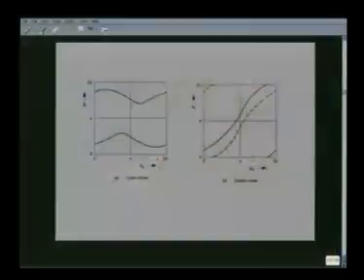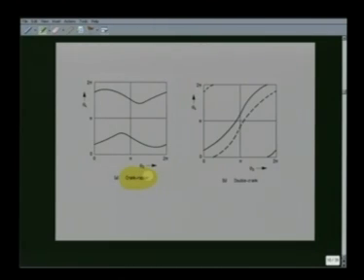For example, here we see what we call a crank rocker linkage. That means it is obviously a Grashofian linkage and a crank rocker, and theta 2 goes from 0 to 2 pi. And theta 4, because theta 4 is the rocker angle, only goes from a minimum value to a maximum value. And there are two branches, one is here and the other is there. Because it is a rocker, again it rocks either from this minimum value to that maximum value or from this minimum value to that maximum value.